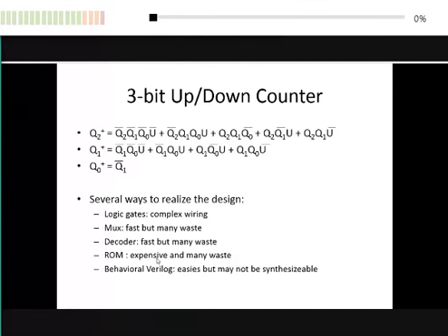All right. Decoder we use normally at the output. But for Moore finite state machine, you don't have combinational logic at the output block, so we don't use it. But other than that, if you have any combinational logic at the output, use decoder. Very fast. Okay.